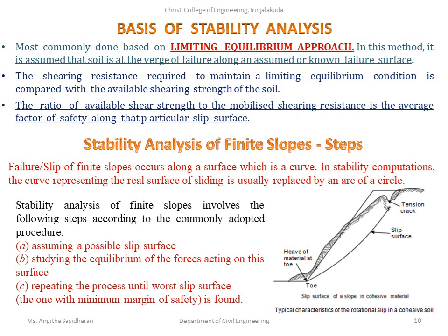Shear strength, the maximum or available shear strength, means how much shear strength is available for that soil. Mobilized shear strength means how much of that strength is actually used to resist. Clear? So we take the ratio of these, and that is called the factor of safety.